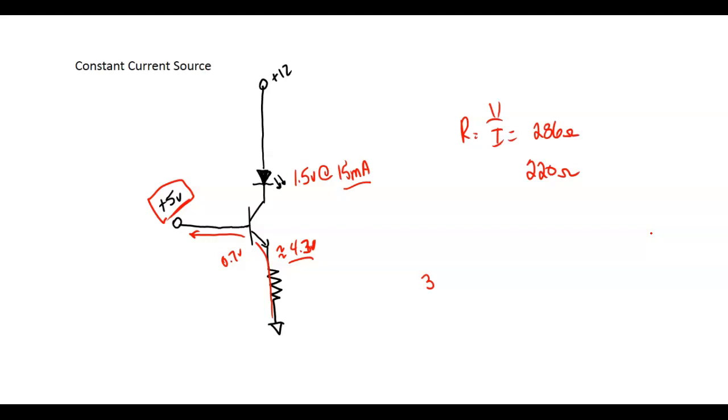So right now, if this guy here is dropping 1.5 volts, and this is 4.3, then how much is the transistor dropping? What would my voltage collector-emitter be? Here, now we're working on this loop right here. I've got to have 12 volts dropped in this loop. So I got 4.3 on my bottom resistor.